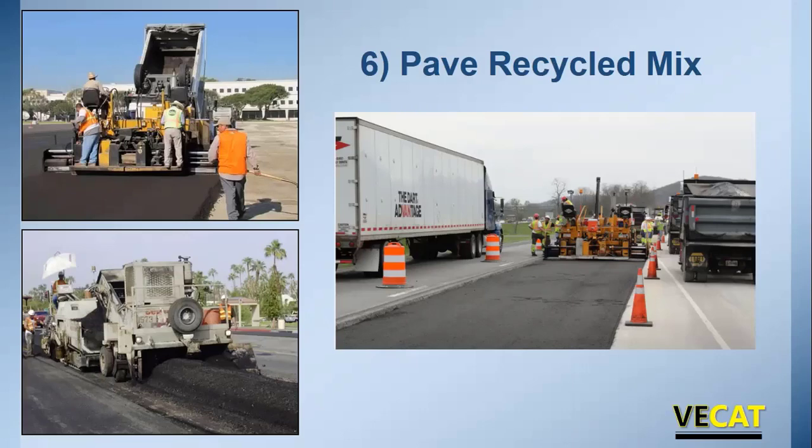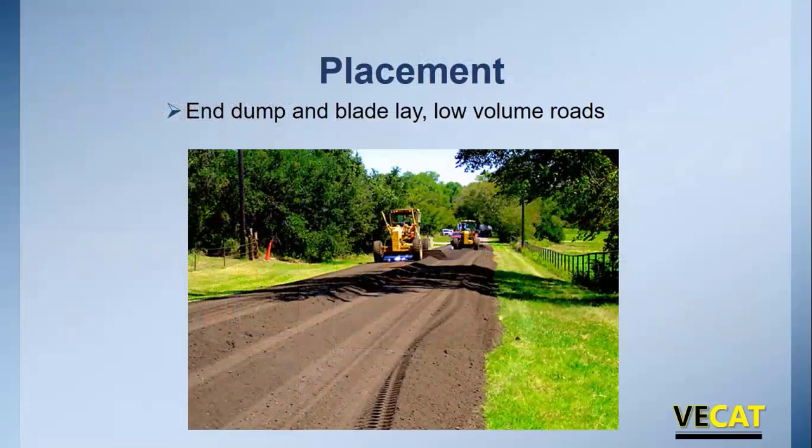Occasionally we bring this cold central plant mix out in a belly dump truck. If we do that, we're going to dump it in a windrow, and we're going to pick it up with a windrow elevator and place it into the paver like you see down there at the bottom. But again, it's placed with the screed just like you would a hot mix. The only difference is I do not want to heat that screed.